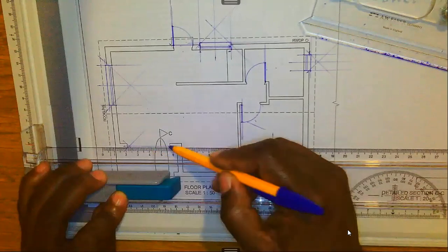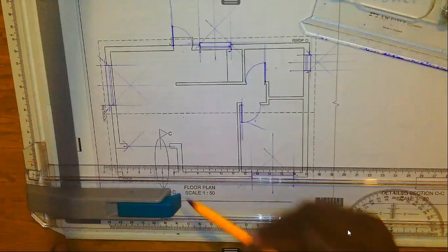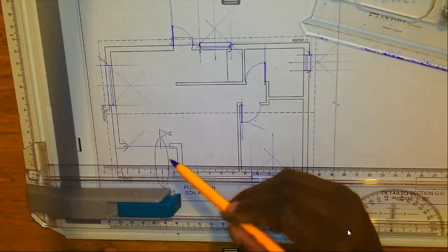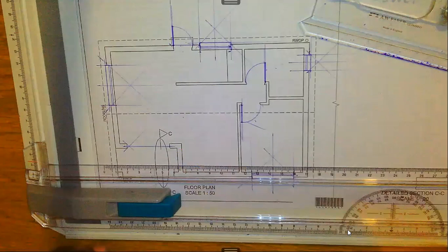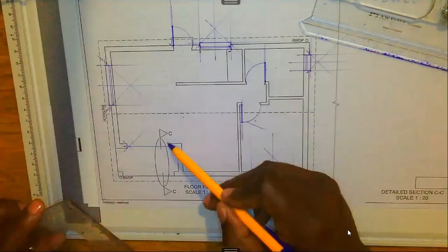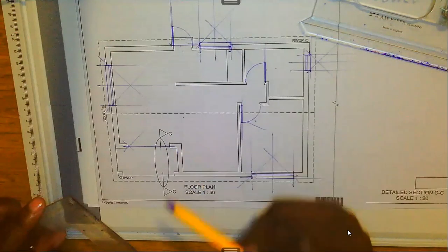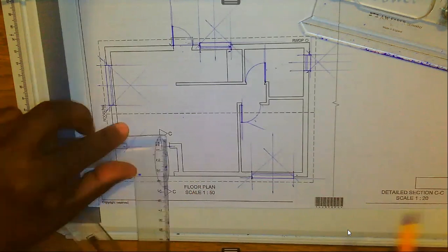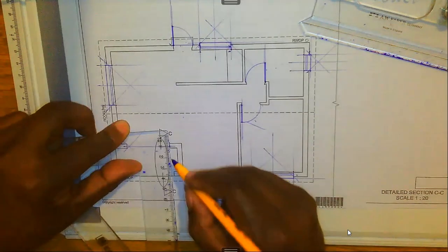Then once we have done that, you measure 50 millimeters this side and 50 millimeters that side. Remember, there is no way that you'll be able to measure 50 from here to there unless you put that 50 to scale. So do not lose sight of the scale. It's critical. You measure 1 millimeter at the top and another millimeter at the bottom like that.